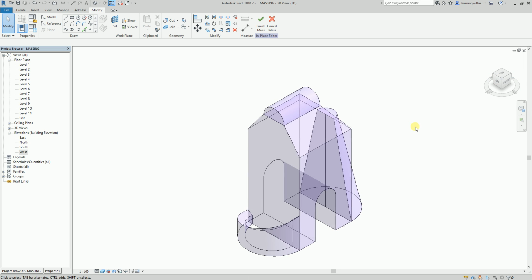During the first phase of the construction, you don't need to create exactly the model. You just need to create some conceptual massing. You can actually do that in Revit, and this is how you do it. On our next exercise, I'm going to teach you how to convert massing shapes to building components. In this exercise, I just showed you how to create mass in Revit.